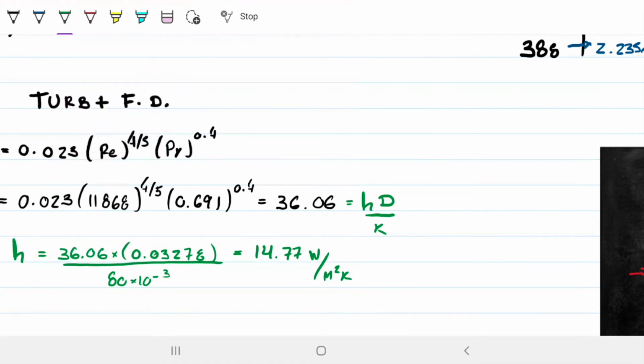Yeah, and it's probably good practice to just ensure we have the right units. Nusselt number doesn't have any units, and then we have the conductivity, watts per meter per difference in temperature. And then down here, because my diameter is in meters, I have meters again, right? So watch out. If this is millimeters, you're going to have millimeters times meters, you're going to have a problem there. So indeed, all our units check out, all good.